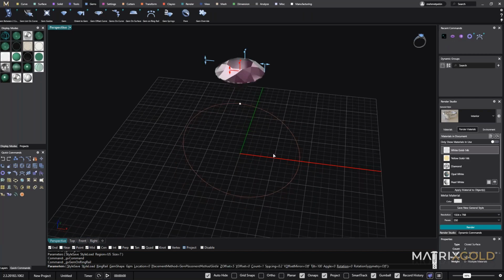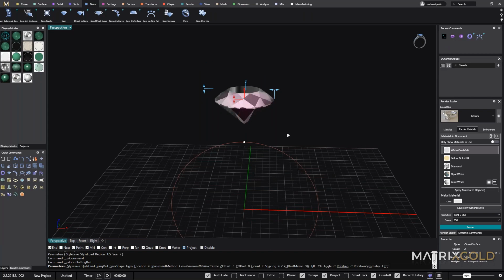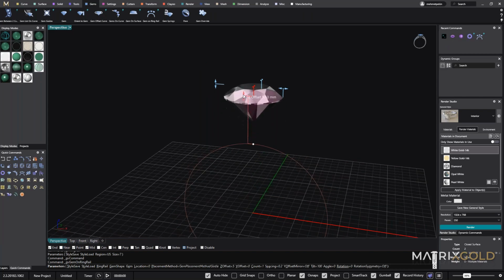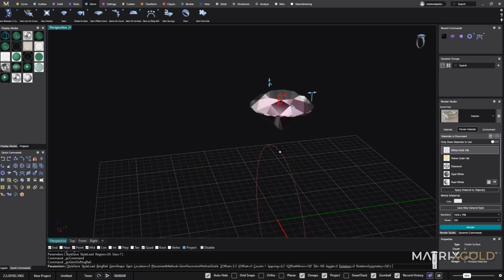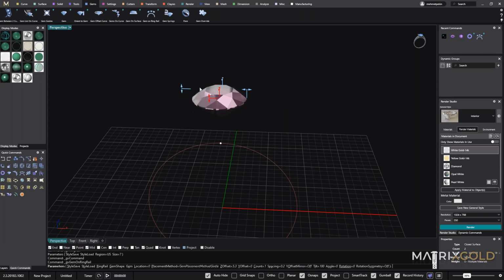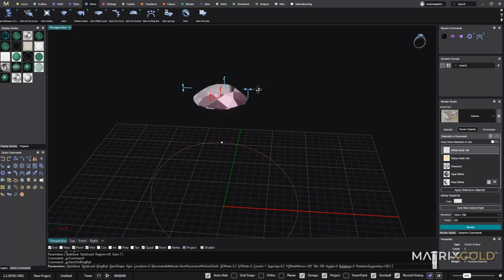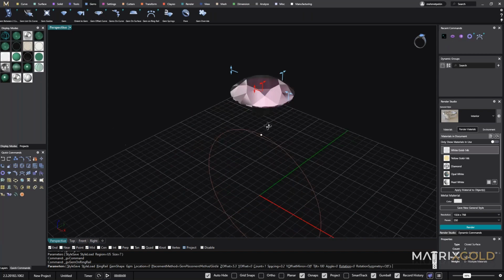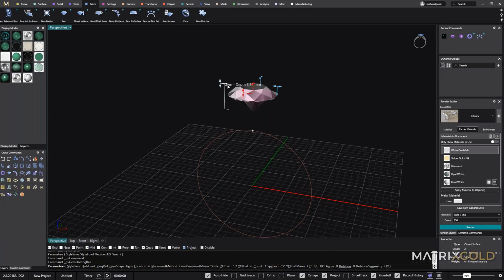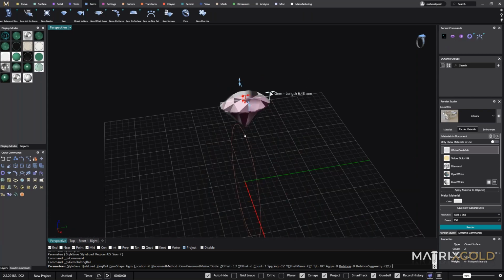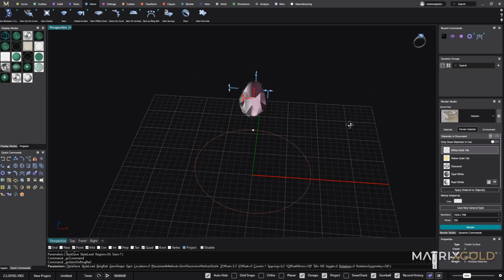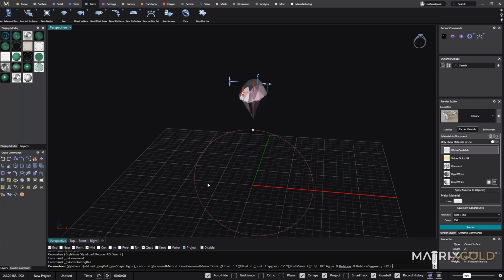I'm just waiting. I want to show you something about the stones. You can move it with that Z offset, or you can move it with that one, and you can resize the gem from here or here. These three of them are the same. They work the same. But when you use the Alt key on your keyboard, you can make it like this. You can resize with the other parts. You can do some stones like that when you use the Alt key on your keyboard.